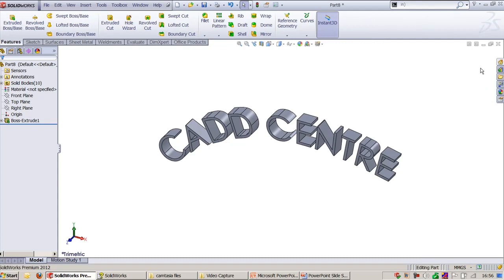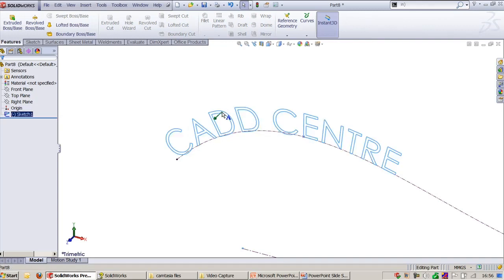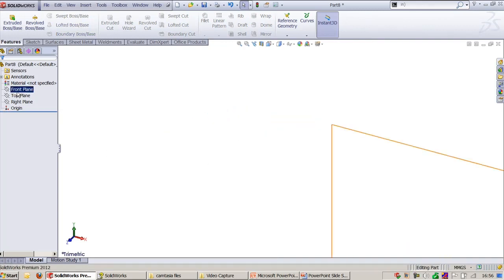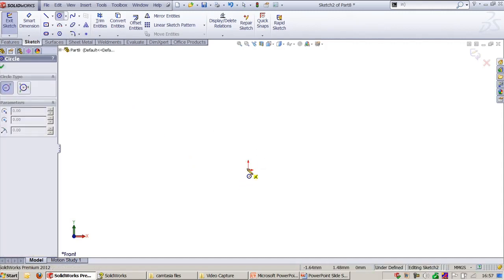That's all about text. Now let us go to the belt chain creation. In almost all mechanisms we require the relation, that is, if I rotate the motor or the pulley, the other pulley which is connected to this pulley has to rotate, and this we can show in the sketcher environment as a layout sketch.